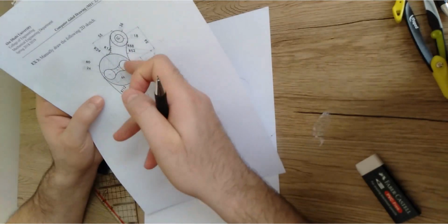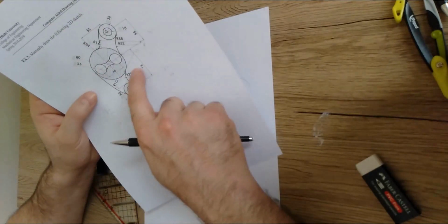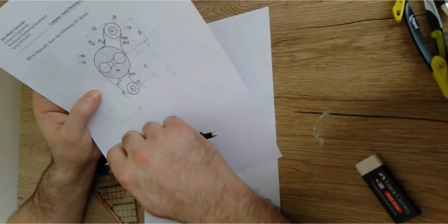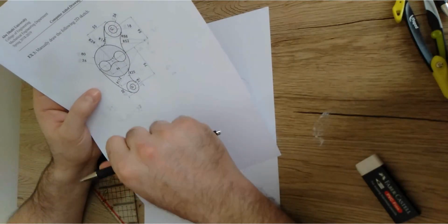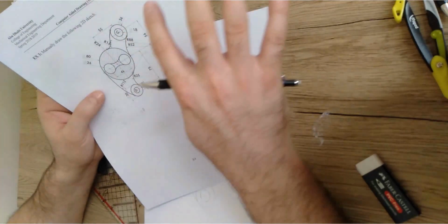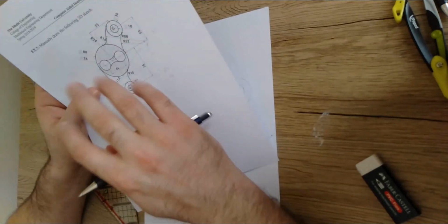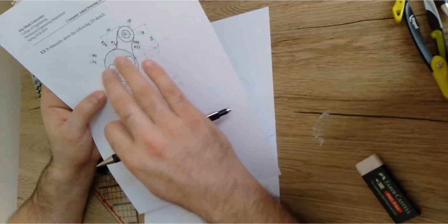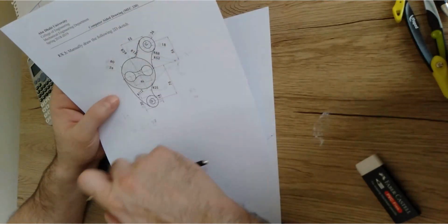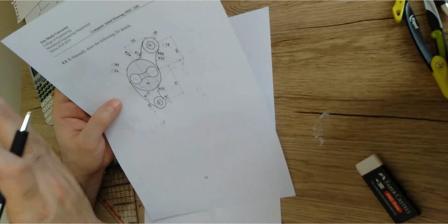And another thing, this hatching should be aligned, all of it together, in one direction and at 45 degrees, according to the ISO standard of engineering drawing. So this hatching is not just for fun. It is not just to give beauty to the shape, or just drawing any lines. No, there are some rules that we have to stick with for drawing these hatchings, and this is what I'm gonna do. So basically, as you can see, it is aligned in this direction.